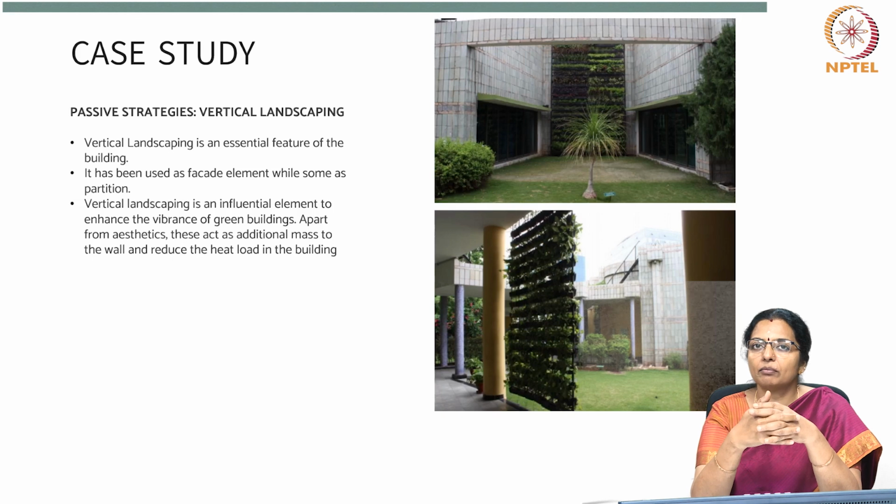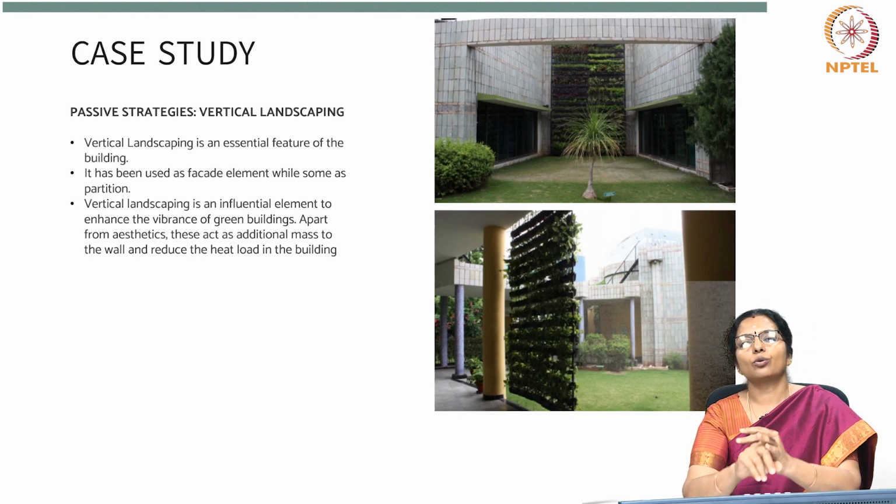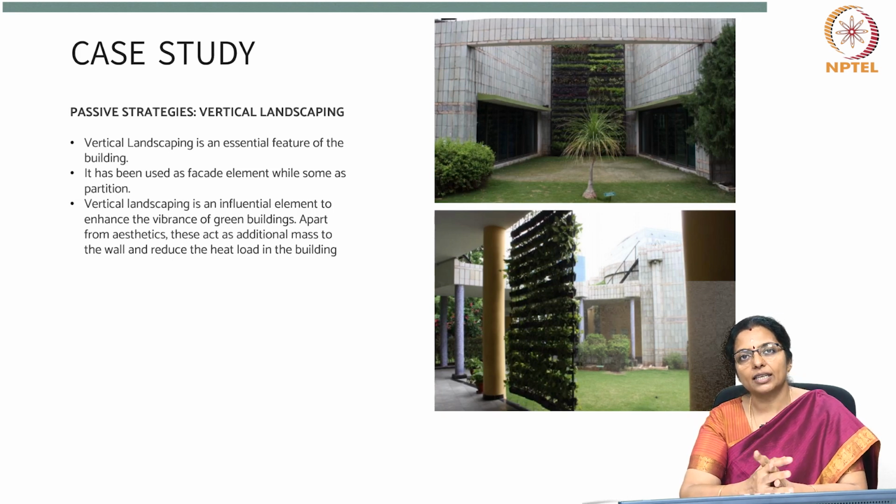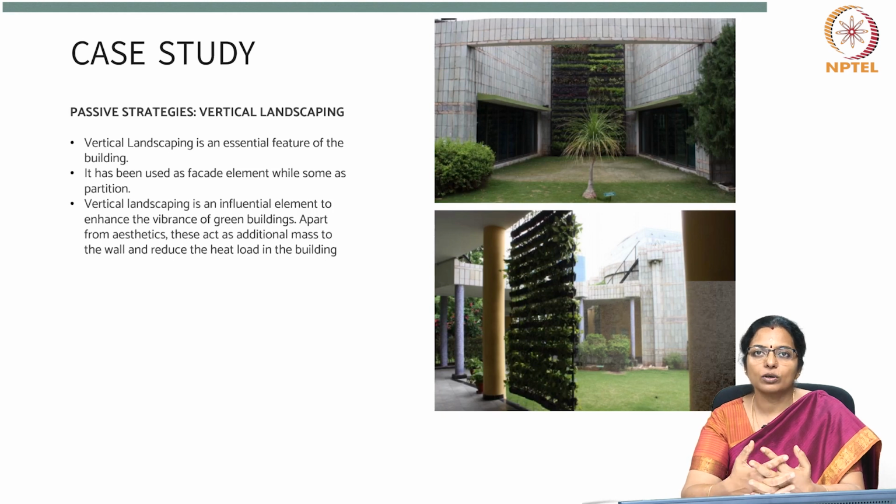The LEED rating for the building has been obtained. This building uses all the simple passive strategies such as appropriate orientation, window size, position, shading of the windows, etc., and some of the advanced passive techniques such as wind towers or green roofs, etc.